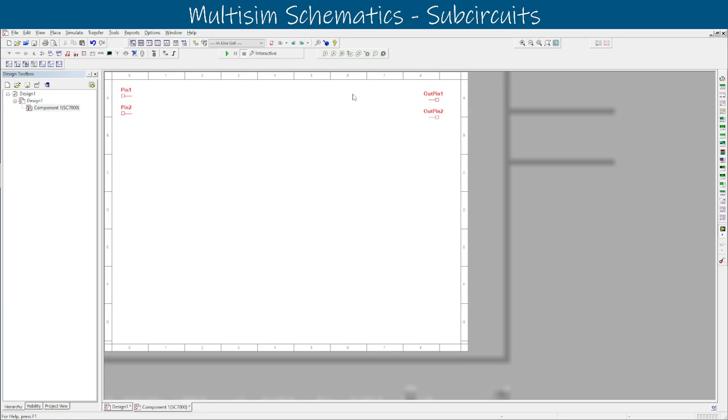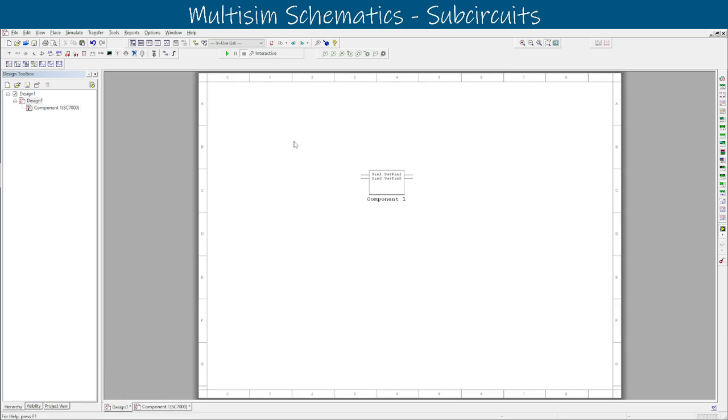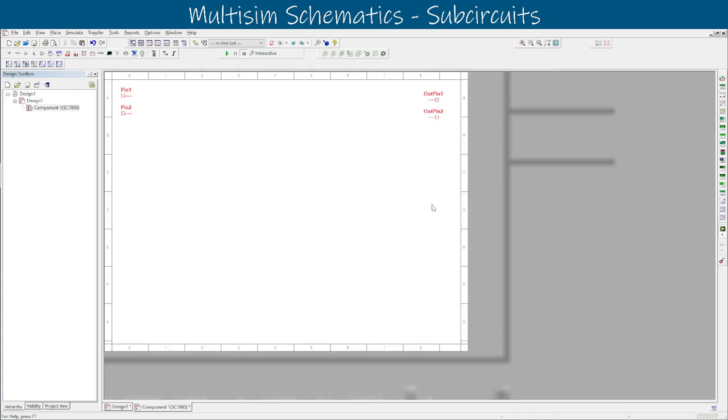Technically, you can build things inside of this also. So if you are looking to build a little low pass filter or something like that, I've built them inside of these subcircuits and use them to simplify my output, where now I just have a low pass filter written in with an input and an output, and then when they click into it, it becomes way more complex with the whole filter on the inside.